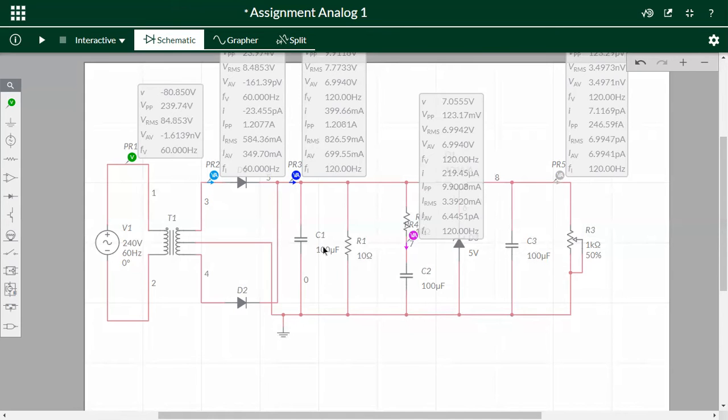As the input AC voltage supply gets to the negative half cycle, the D1 diode gets reverse biased, but the D2 diode is forward biased. Throughout the negative half cycle, the flow of current in the second diode gets to the filter to charge the capacitor. But the capacitor charging occurs only while the applied AC voltage is greater than the voltage of the capacitor.